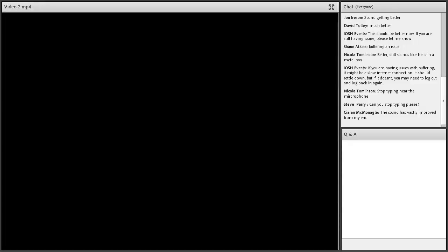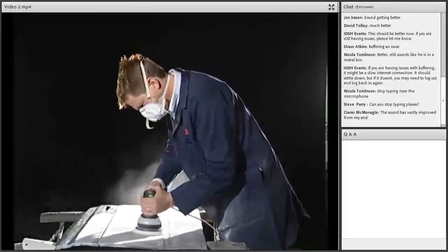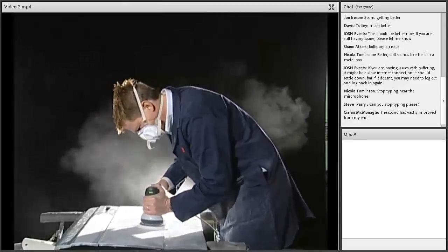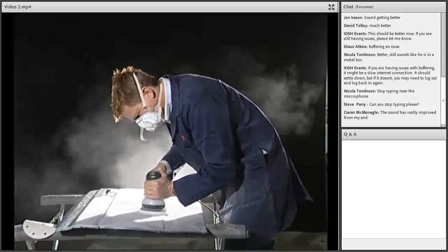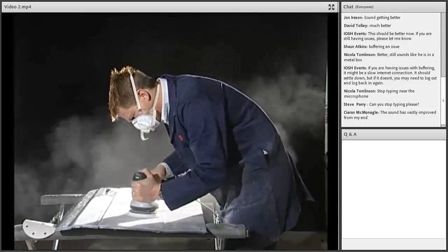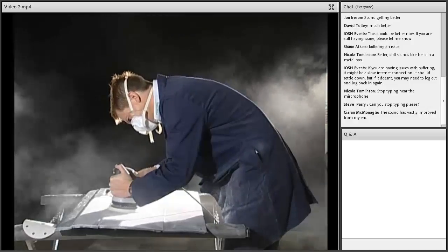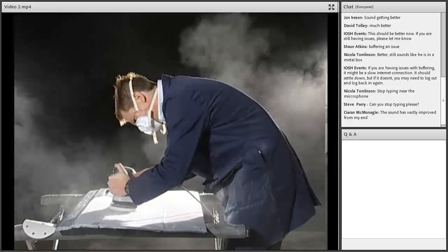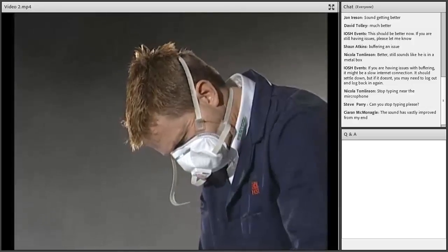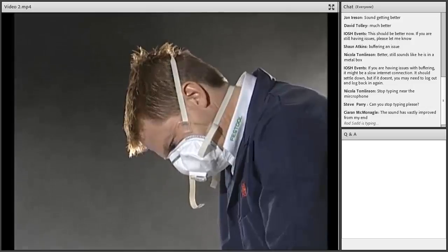This is a video that's in exactly the same conditions. The only difference is backlit. And what you can see here is obviously the really, really fine dust is going up straight away. Because it's so small, it's staying in the air. It's not coming up and straight down like heavier particles would do, which is just staying up there and lingering around. As a consequence of this, fine dust can stay in the atmosphere for a long time. If you dry sweep, it puts it in the atmosphere and then it stays there again to affect anyone who kind of walks into that area.